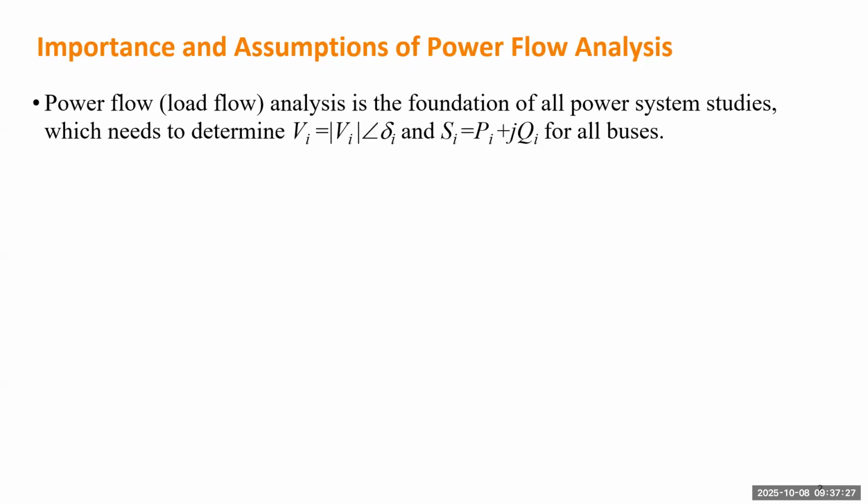Definitely, you can add some additional requirements. For instance, I know the power flows right now for the current system, but I want to open a line. If I open the line, definitely the current on the line will become 0. So the voltage on both sides of the line will change. So we need to recalculate the power flow, right? That also indicates some applications of power flow analysis.